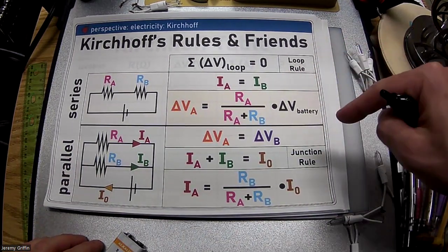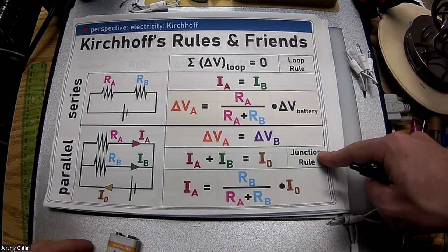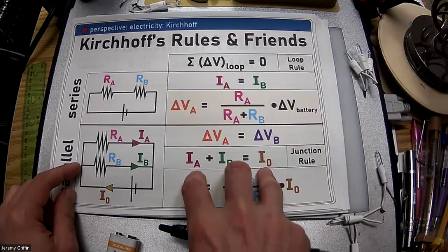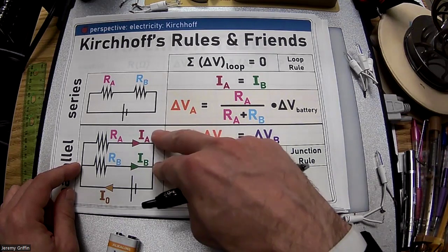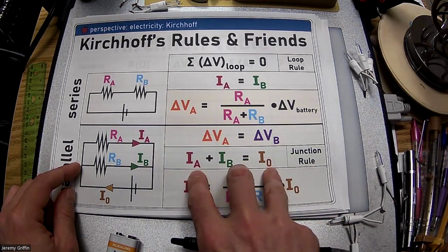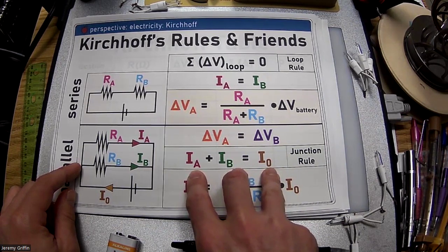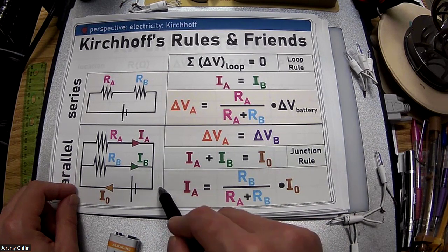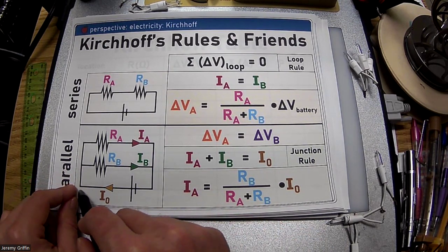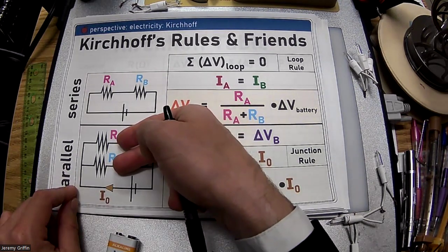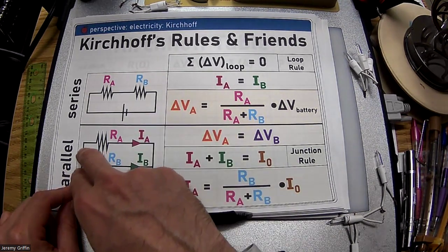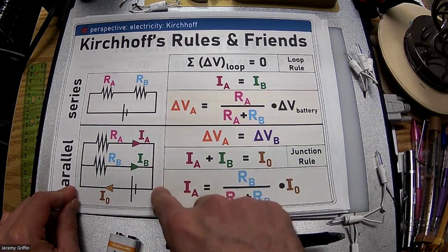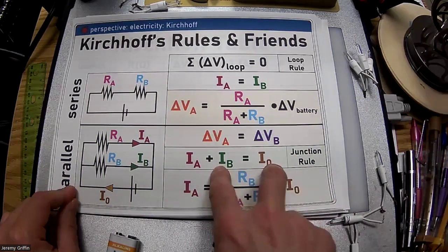Okay, and since I'm going on a textbook, let's hit the junction rule. The junction rule says if you have a junction, here's a junction, the current's coming around, the current is going to split such that the 2 individual currents on these 2 new branches sum to the original current. So it's a conservation of charge concept. Suppose you have 9 amps, I'm going to switch over to amps. Say I have 9 amps come this way. Now, if these are the same resistance, say 1 ohm and 1 ohm, do you guys think it's going to split exactly half and half? It's 4.5 amps, 4.5 amps, but it still has to add up to 9. It comes back together. In fact, it makes 9 going back to the battery. That's the junction rule. Okay, so you guys go with those?